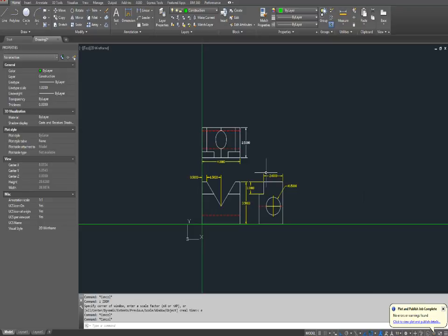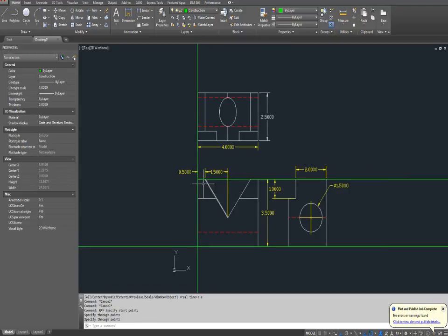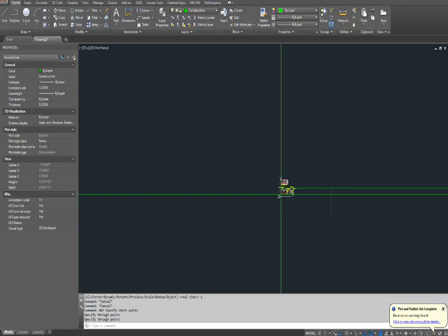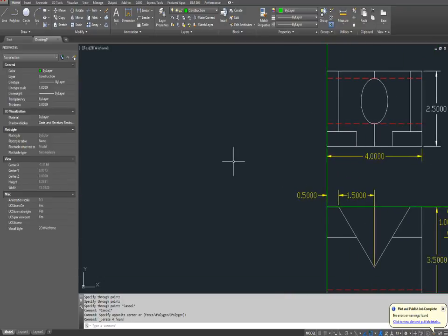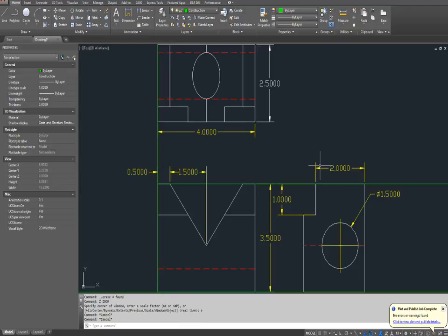Similar to the X line is you can use ray. Select on ray, I've got my ortho turned on, and you can see it's got a fixed point on one end, but it continues out forever. And if you don't have your ortho turned on, then you can see it's just any angle you need it to be. Pretty handy. I think that's pretty handy when I like to make my miter lines.